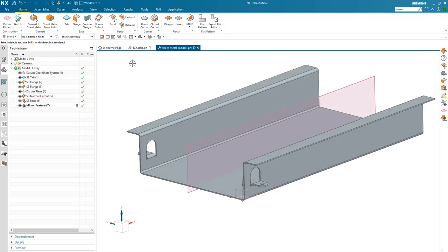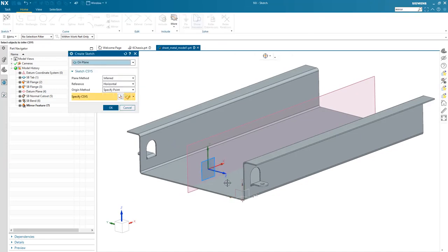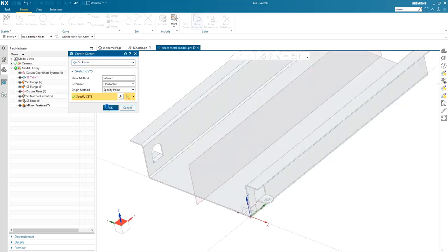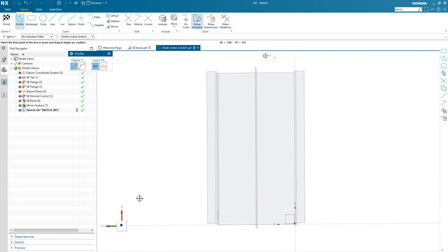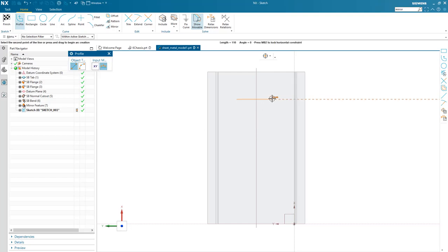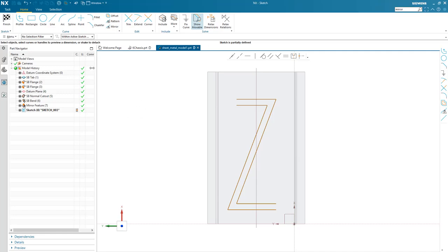The next thing we want to do is create a gusset. A gusset basically, oh no, we're going to create a dimple first. Dimple basically, where do you want it? So we want to have it at the bottom of that, and then it could be any shape design that you want. So we want to just create some very simple shape. We're going to quickly just create kind of a zigzag arc of that, or lines of that, and then we want to create an offset of that, and it could be punched through to the upper or to the lower, it doesn't matter. So in this case, I want to just create an offset, and then we want to close off those end edges or the end lines, so to speak.